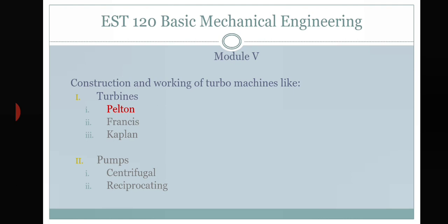So always keep in mind the definition for turbo machinery, where we are having an interaction between a fluid and a rotor, and you will be definitely changing the fluid momentum and potential energy of your fluid in a turbo machine. You can have two types of turbo machines, like power generating turbo machines like turbines, and you can have power absorbing turbo machines like pumps. So in pumps, we discussed more on turbines till now. What a pump does is the pump can transfer the rotation of the impeller to the fluid so that the fluid can flow.